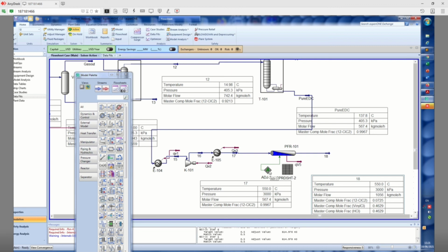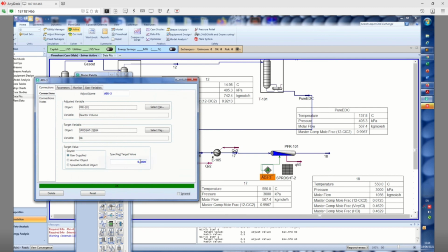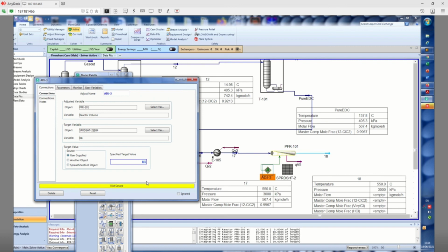So I will change the residence time. In the literature, they say they work for 60% conversion, because if they target 100% conversion, then you have to wait more time and it's going to degrade your product. So let's stick to some low value. Let's put 0.1 and see.